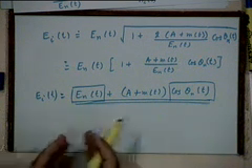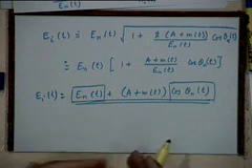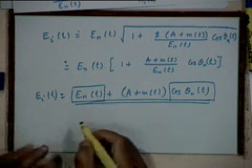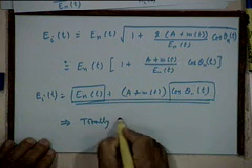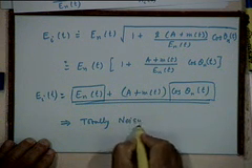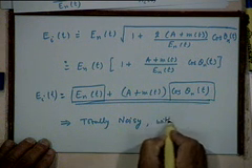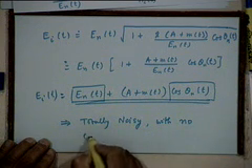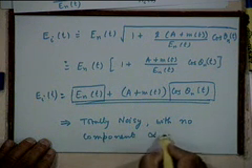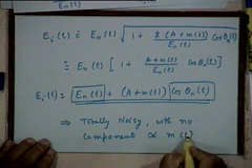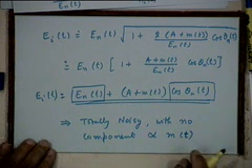So, it is not even a signal plus noise kind of an expression. So, essentially the envelope is almost totally noisy, right, with no component which you can consider as being proportional to the message Mt, which is our desired signal.